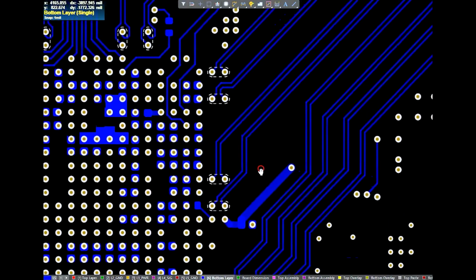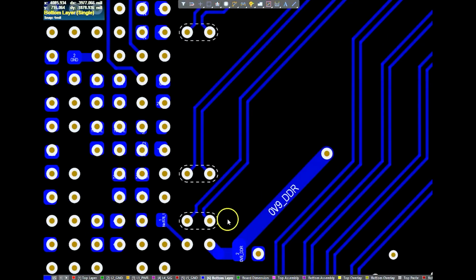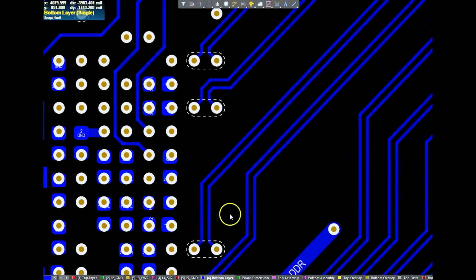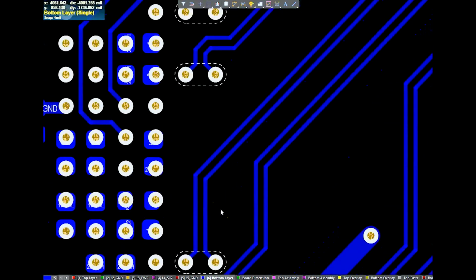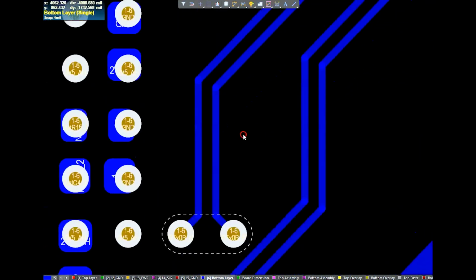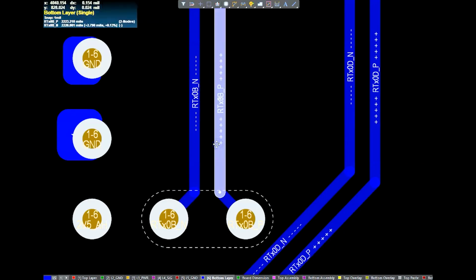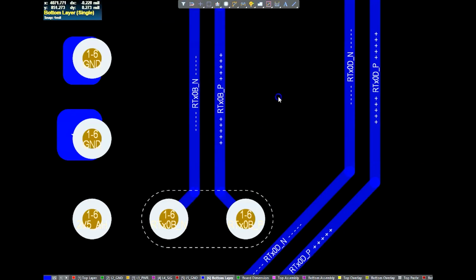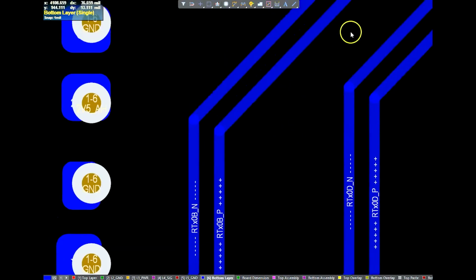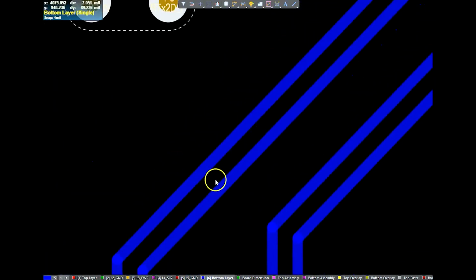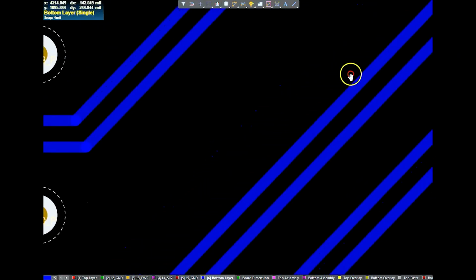What we're looking at here is a PCB layout with some differential pair routing, and you can usually tell that it's differential pair routing because if somebody named the nets correctly, if you zoom into the net names, you'll see that they have an underscore N and underscore P here. So this is your cue that this is a differential pair. This side carries the positive voltage, this side carries the negative voltage. And the way that they're routed is they're routed very closely together, the spacing is maintained, and then the width is maintained throughout the length of the route.